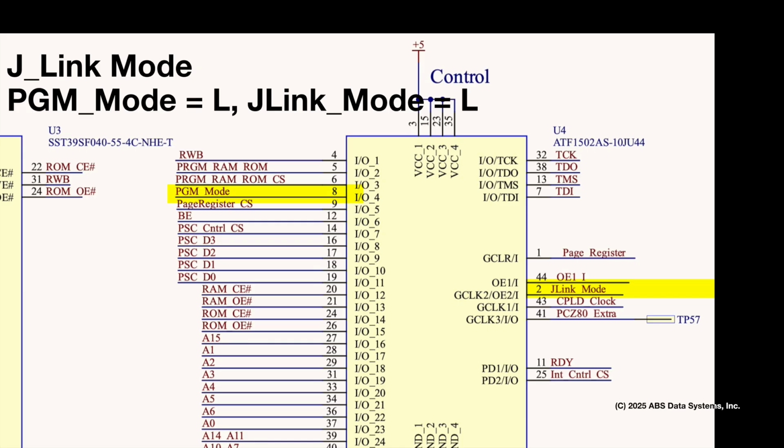This will allow the programmer to single step the 6502. After each step, the programmer will read the address and data buses as well as the RWB line to determine what happened during that clock cycle. Since we're evaluating the address and data buses and the RWB, this gives us the ability to run code to a specific location and to set breakpoints.